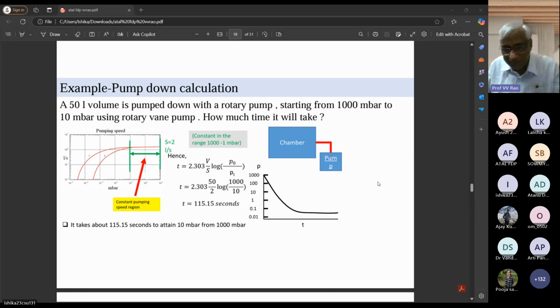They are mostly removing the gases coming into the chamber by evaporation, by degassing, by leaking. They are much more compared to the remaining micrograms of gas which were there in the beginning in the chamber. These are milligrams. So high vacuum pumps are not pumping the chamber gas.